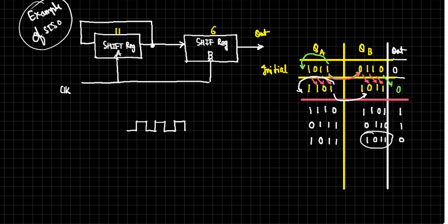You feed the data or insert or copy the data or receive the data serially, but once serial copying has happened and shifting has happened, all the data is available at a time. How can you have that? Can you draw the circuit for that? It's very simple. You need to draw the circuit for serial in and parallel out, SIPO. Draw it quick.